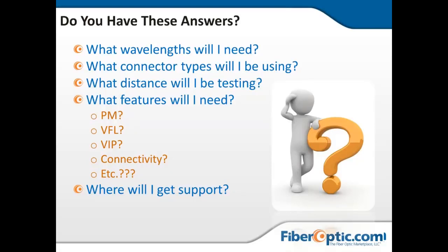There's a couple reasons why, and again we'll get into that, with damaging the front end of the connector, being able to see the first connector to make sure you have an effective connection, and things of that nature. But you will need to know that if you don't have a launch box that has the appropriate connector and appropriate mating sleeve, then maybe you have to connect to it just to test continuity or get some sort of basic reading.